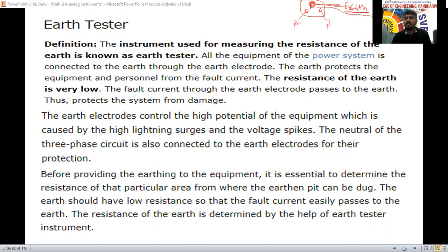Suddenly if you are using the iron box, what do you do? You are going to touch the iron. You are going to use the washing machine. Just think, the outer steel part is there and you touch that one. You will experience an electrical shock if any leakages are there. If earthing is there, you are not going to get the electric shock, because it is bypassed to the earth. So to avoid that, everywhere earthing is there.